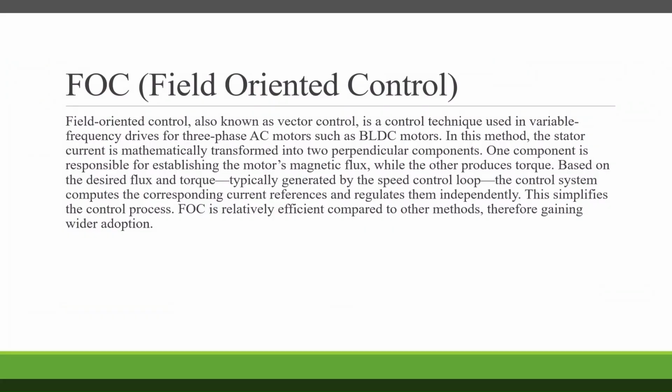What is FOC? Field-oriented control, also known as vector control, is a control technique used in variable frequency drives for three-phase AC motors, such as brushless DC motors. In this method, the stator current is mathematically transformed into two perpendicular components.